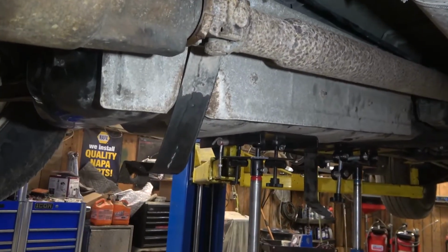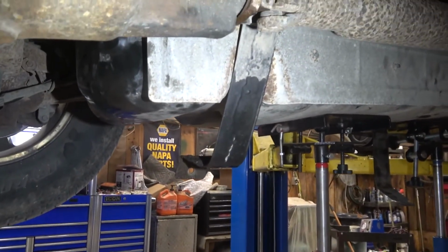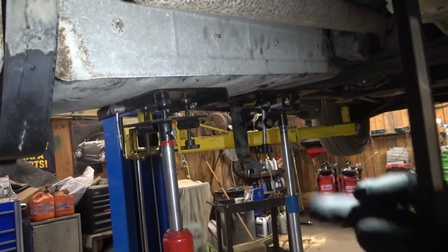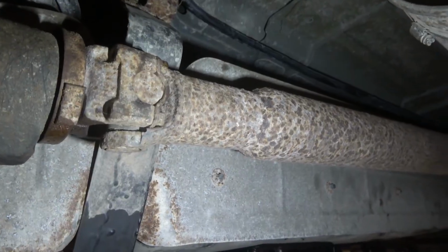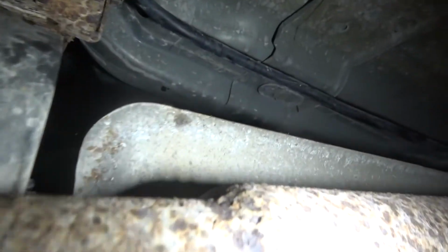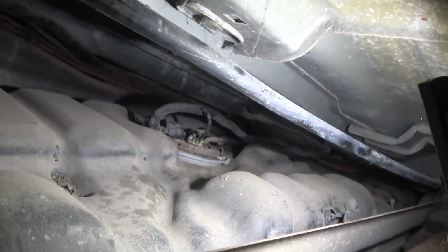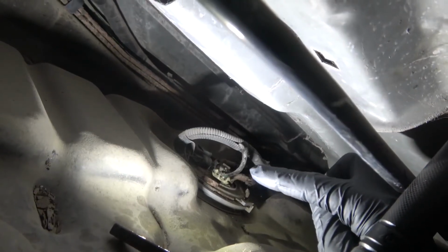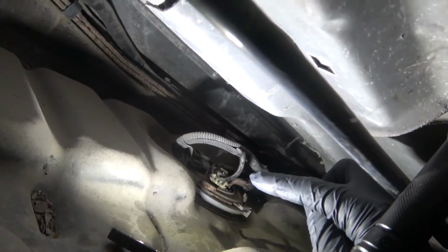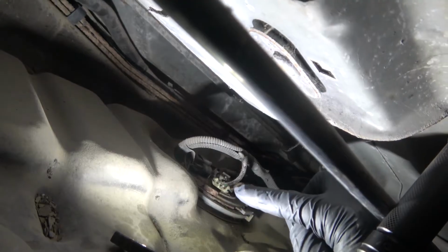We have lowered the fuel tank. As you can see, I got this fuel tank strap off. The other strap over there is off. So now we can get access to the fuel pump sending unit. So if we go up here, you'll see that now we have access to the fuel tank pressure sensor. This electrical connector over here is the electrical connector of the fuel tank pressure sensor. As you can see, it has 3 wires on it.